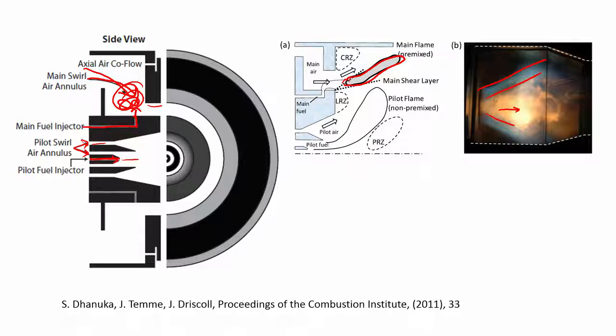So, this cuts down the emission to a great level because of the presence of the premix flame, and so even with this liquid fuel injection you can manage to get essentially a premix flame on the main sides, but then that has to be stabilized, and there needs to be a continuous pilot flame for the reasons already discussed, because your power requirement can vary, etc.